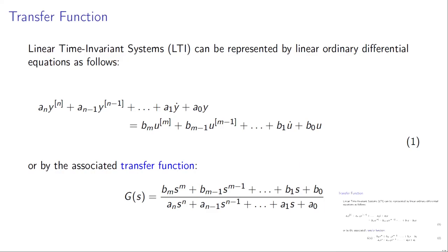So how do we get the transfer function? First, you need to have a mathematical representation of the system. Usually what we have is a linear ordinary differential equation, as in ODE 1. So we have a differential equation relating the output y, the derivatives of the output y, with also the derivatives of the input u. Okay, a and b in this case are only the coefficients of these derivatives, and this here, for instance, is representing the derivative of order n.